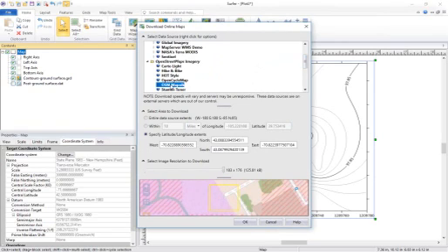And so I went ahead and selected the server. And since I set my coordinate system to CRS for my map and the layers, Surfer automatically populates the lat long and does a conversion for us. It populates the lat long extents, so we know where and what tile to get from the server.